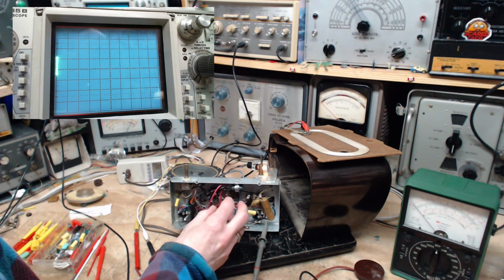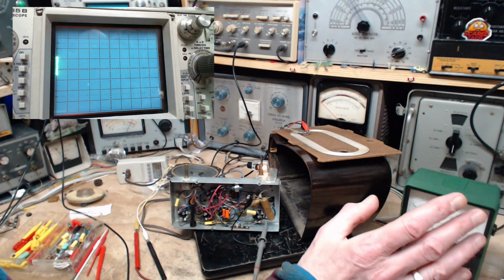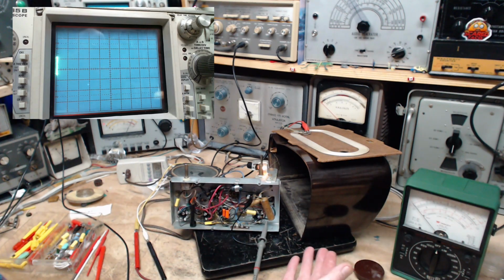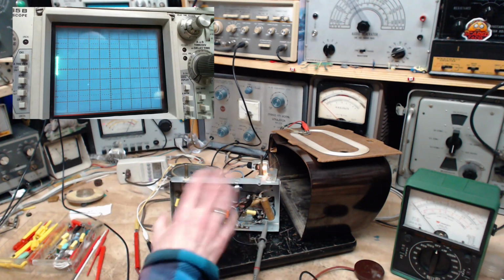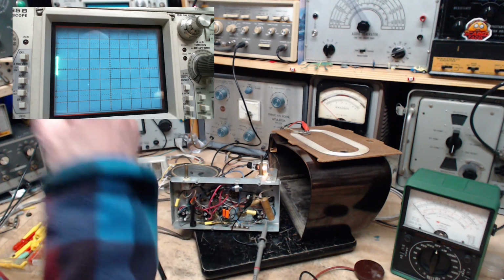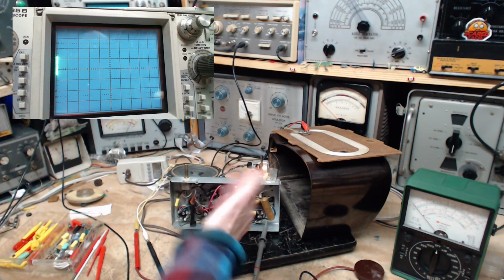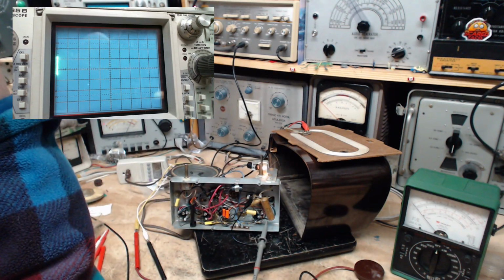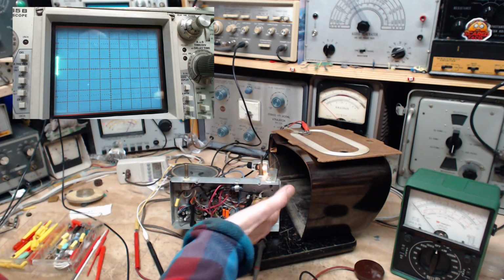Now, much of the radio is tuned to 455, so down the way, other frequencies are not going to make it. Only 455. So if this thing's resonant at, let's say, 400, you're not going to hear anything out of the speaker that has something to do with 400. In other words, if I make this thing resonant at 400 somehow, I'm not going to find it this way, I think. The radio itself is not going to play a sound and convince me, oh, this is not right.